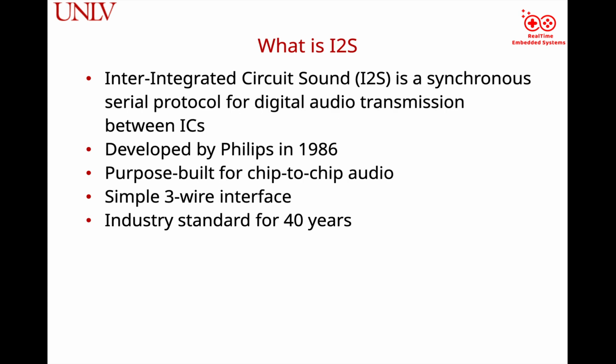So what is I2S? I2S was developed by Philips in 1986 and has become an industry standard for nearly 40 years. It's a synchronous serial protocol using just 3 wires: clock, word select, and data to transfer digital audio between chips. Because of its simplicity and reliability, I2S remains the foundation for most embedded audio systems.